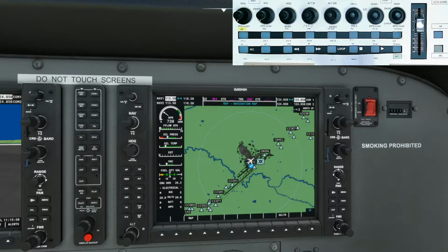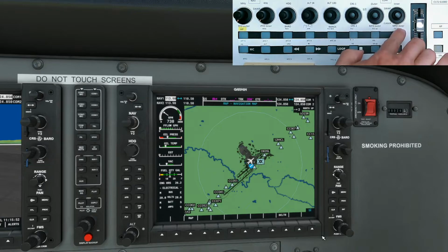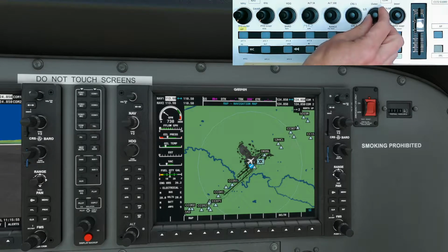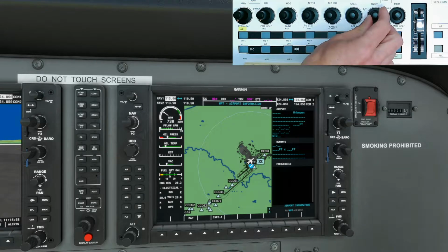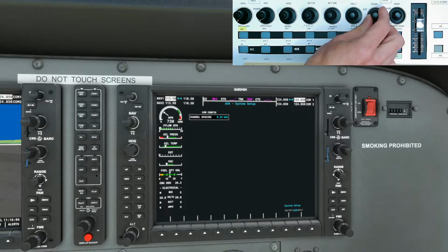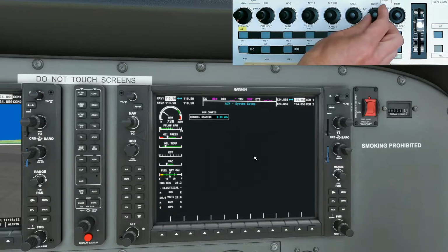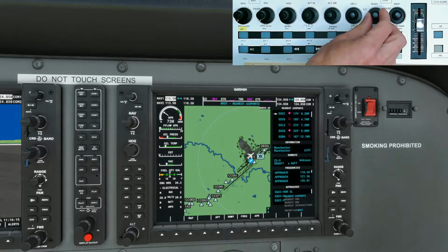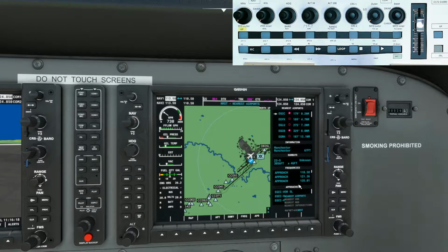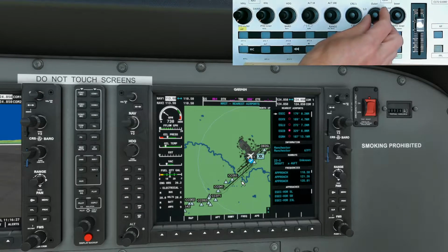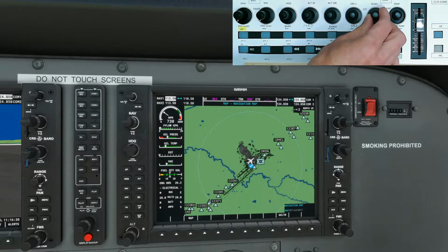So again, looking at these two knobs here, one turn of the outer knob here brings up airport information. Another turn brings up the only setting that we can configure, which is the spacing of the frequencies for the radio, but we don't need to work with that. Next turn, again, look at the nearest airports, but now we've got the information that we need, frequencies and the runways information, much more useful for us. And then back to the map again.